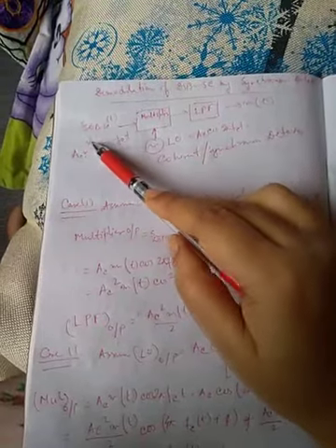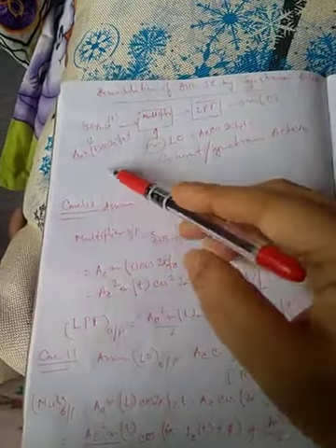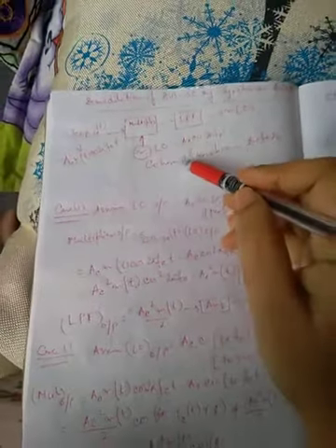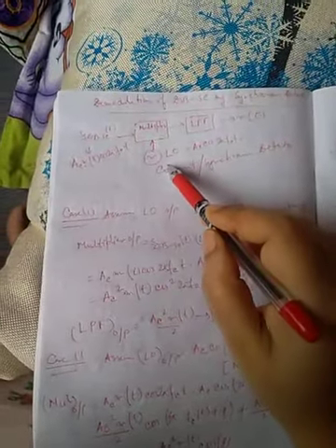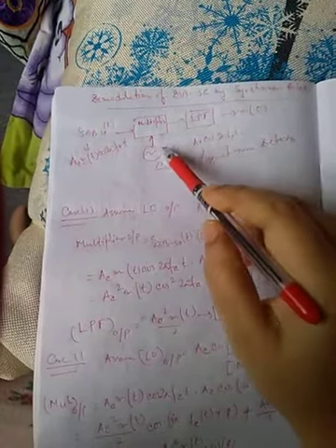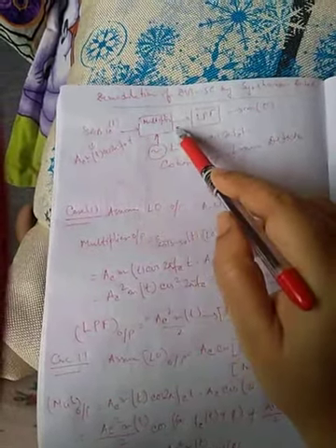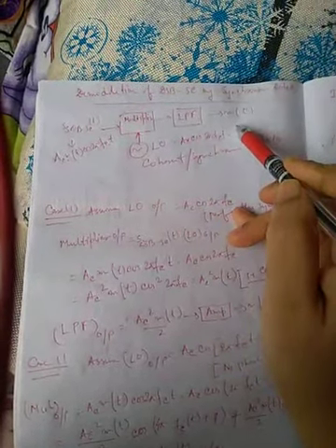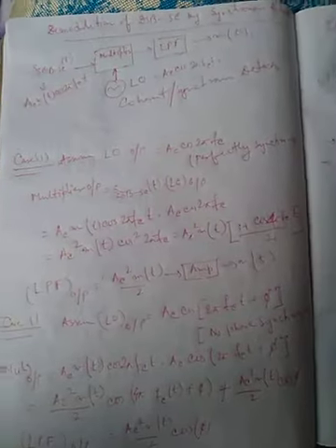So here is the double sideband suppressed carrier signal, which we have already explained, Ac m(t) cos 2 pi fc t, and here is the local oscillator generated carrier signal Ac cos 2 pi fc t. It is coming to a multiplier circuit, then it is going to the low pass filter, and finally it is generating the desired message signal m(t). Now I have taken two cases.